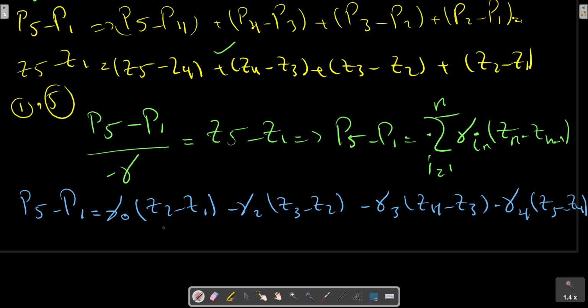No additional simplification is possible on the right hand side because of the different densities. Notice that we have placed the fluids in order from the lightest on top to the heaviest at the bottom. It is the only stable configuration. If we attempt to layer them in any other manner, the fluid will overturn and seek the stable arrangement. Pressure increase downward is calculated with the formula on this page.